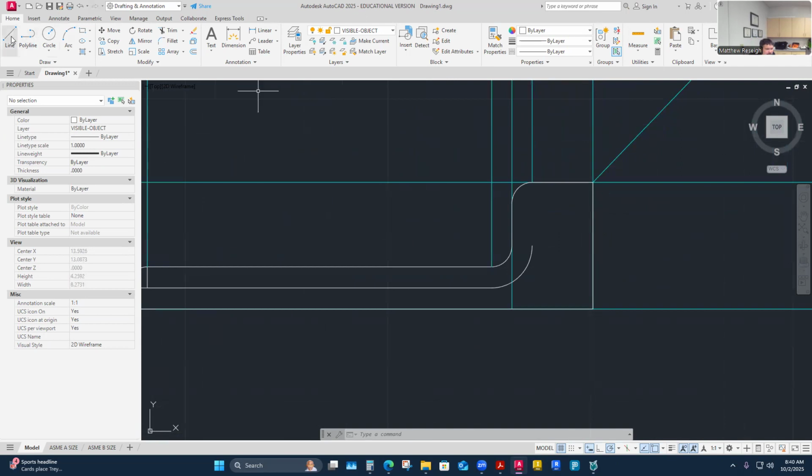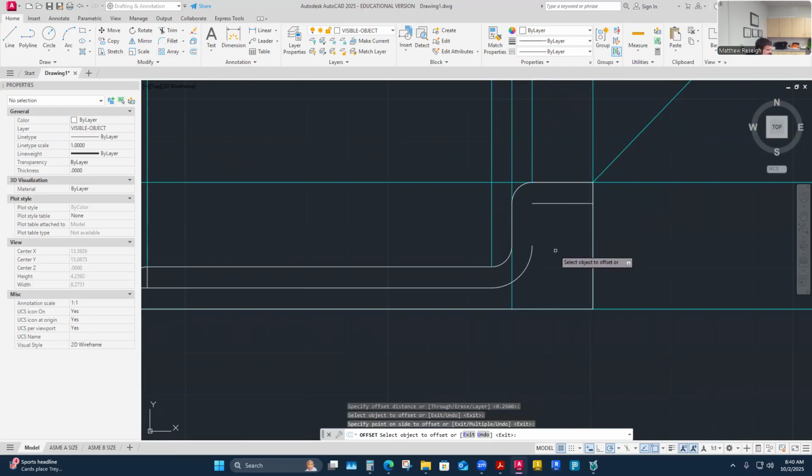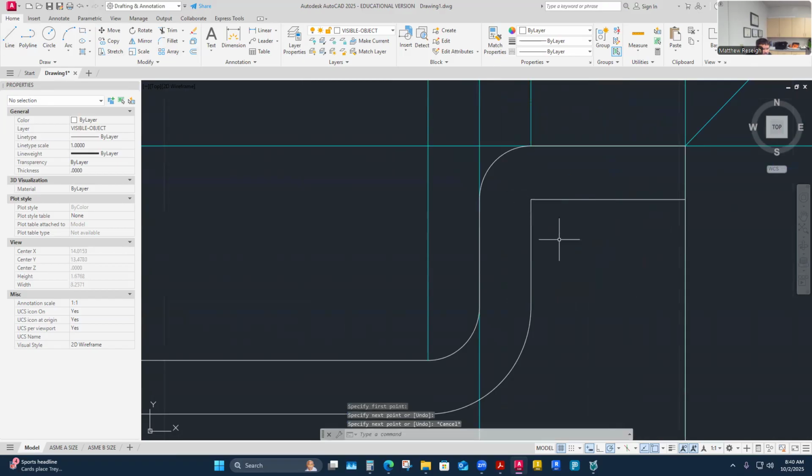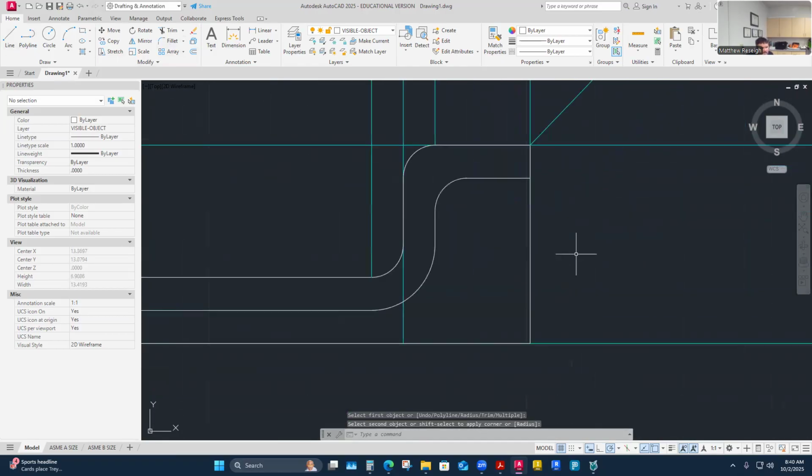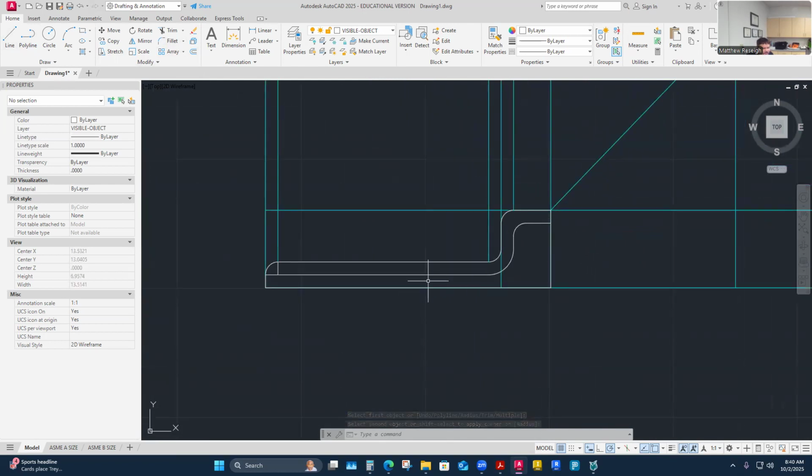But I think what I'm going to do here is do an offset. I still got my 1/4 inch offset. If I do this offset, it would offset this one down. And then I need to draw a line that goes up to there. And then can I actually fillet that? Maybe not. It's a fillet with our same radius. Yeah, so where it wouldn't allow me to offset that, and it might not exactly look like that, but that is that bevel that's kind of weird to see.